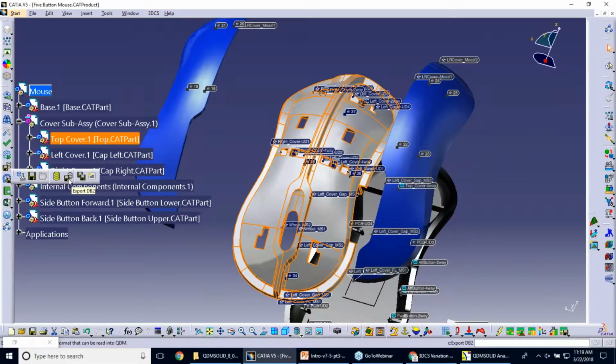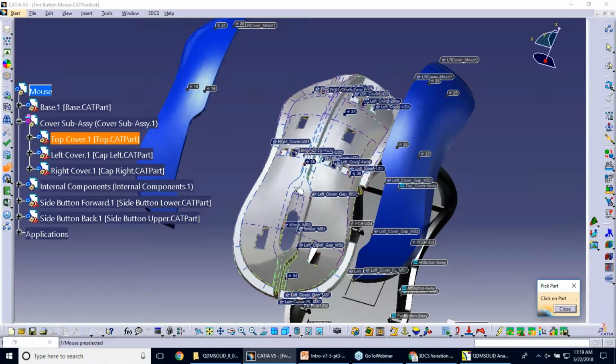These points are the points that are used to assemble the buttons, and they're the points that are used in the measurements. So the idea here is if you did a 3DCS model, these are the points that we want to measure when we start making that top cover, because they are the functional features on that part that are needed to validate the total assembly.